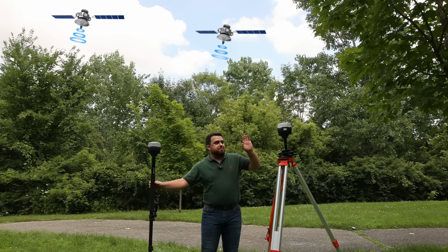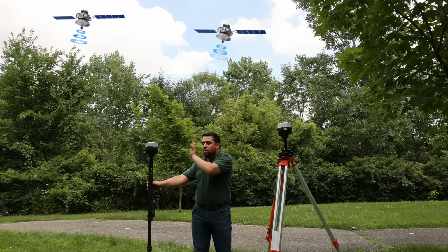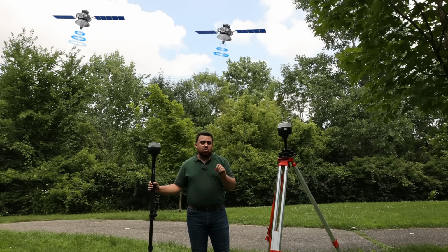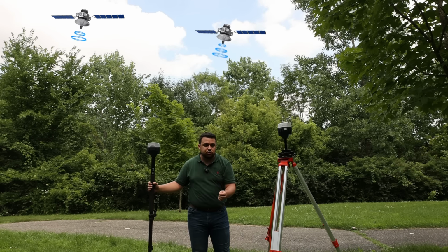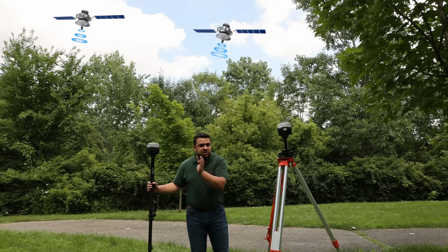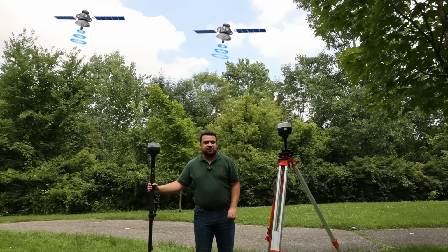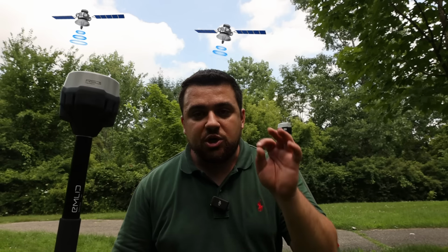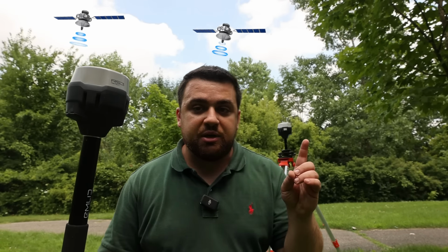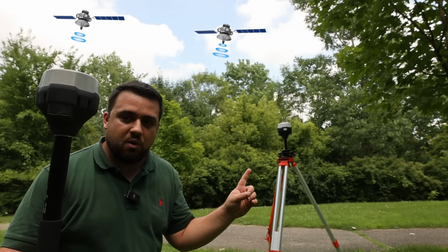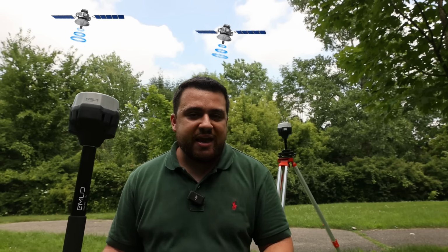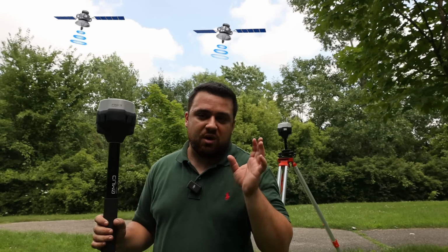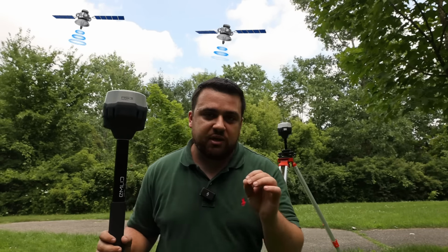Now, it's important to note that both the base station and the rover need to have clear visibility to the satellite in order to have a fixed solution. So for your RTK corrections to be fixed, you need ample satellite visibility and a connection between the base and rover. If you don't have satellite visibility, but you do have a connection between base and rover, then you have what we call a float solution. A float solution generally has about 1 meter of error, but is definitely not survey grade accuracy.